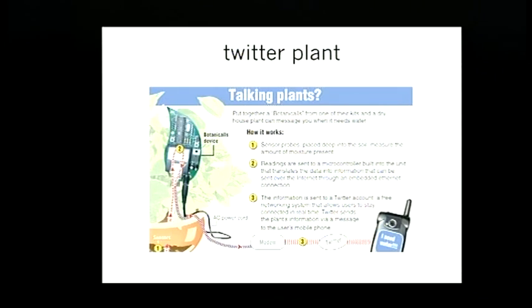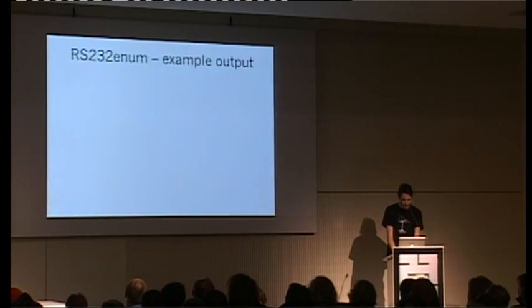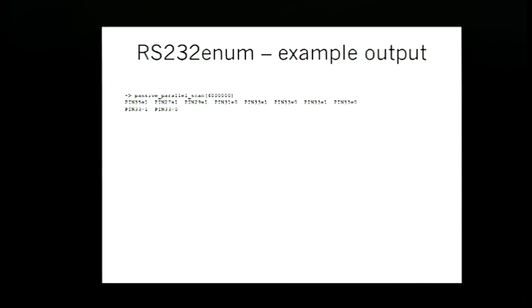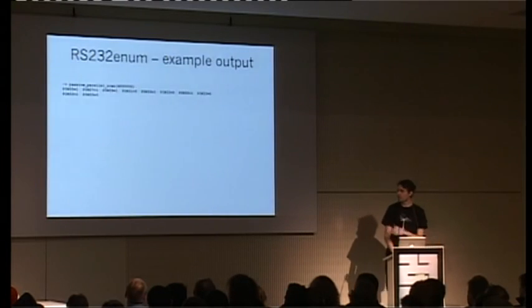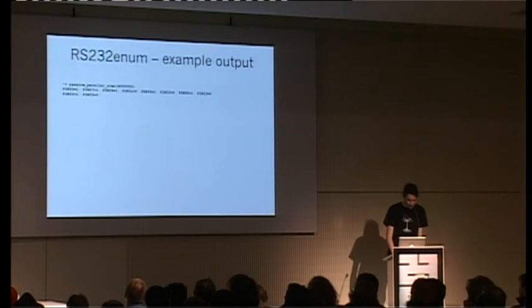So there's all sorts of very simple things that are coming from different art students or designers that start out with Arduinos. So here's some example output of a serial scan. There are 3 basic scans. One is passive parallel. It's basically like a logic analyzer, but a very slow one. It just shows which pins change state. So if there was serial activity happening just on boot, then you should see a lot of activity on a particular pin. This particular output doesn't indicate a lot of activity over the period of 4 seconds.